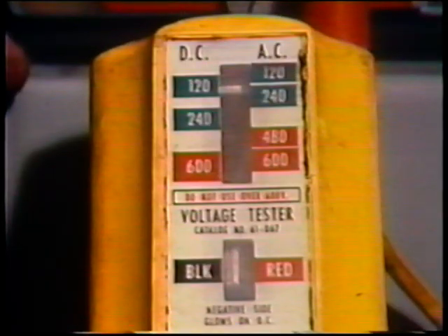The reading shows that voltage is present. The fuse is good. The electrician should not replace the bad fuse with a good one until he discovers what caused the fuse to blow. Therefore, his task is not yet completed.